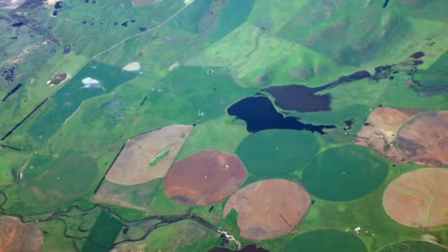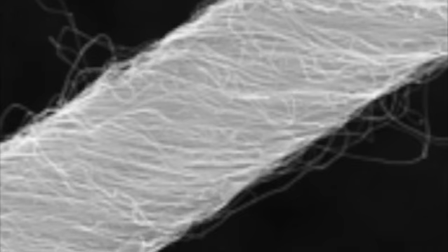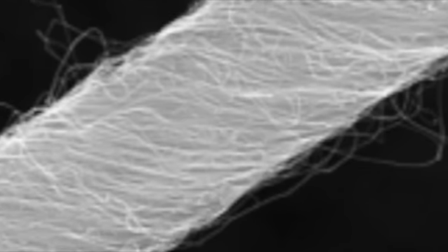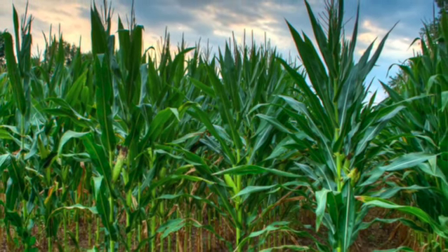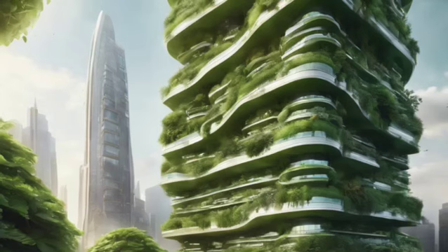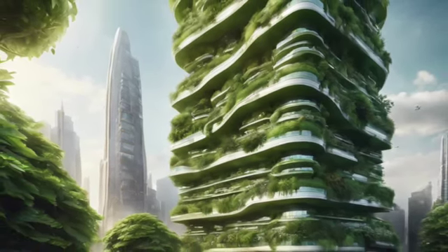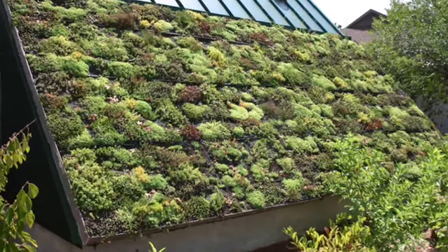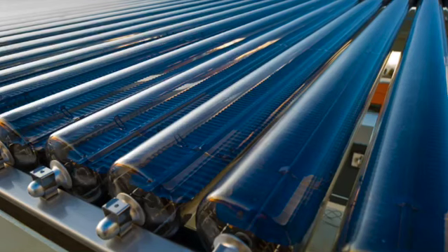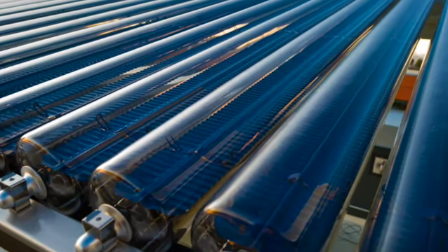Incineration process. Incineration involves the controlled burning of solid waste at high temperatures. The heat generated during combustion is harnessed to produce steam, which then drives turbines to generate electricity. Energy recovery. The primary purpose of incineration is energy recovery, and it reduces the volume of waste by up to 90%. The heat produced can also be used for district heating, providing warmth to nearby buildings.